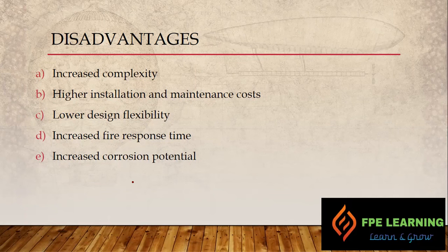Most of the regulatory requirements limit the maximum size to 750 GPM for an individual dry pipe system, unless additional components and design efforts are provided to limit the time from sprinkler activation to water discharge to under 1 minute, or 60 seconds. It should reach the most remote location within 60 seconds.